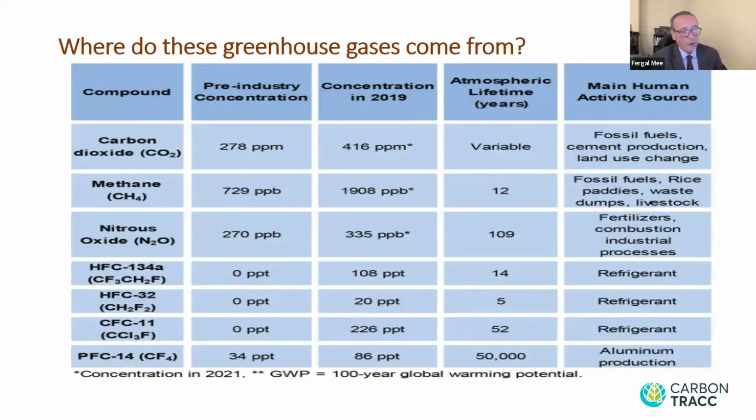And two which aren't shown here on the global warming chart would be SF6, sulfur hexafluoride, which has a global warming potential of 23,500. It means 1 ton of sulfur hexafluoride SF6 emitted to the atmosphere has the same global warming capacity as 23,500 tons of carbon dioxide. So that's a significant gas, which is used in the electrical industry. Aluminum smelting is again, and non-ferrous metals.